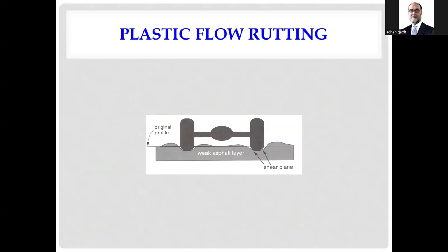Now how do you see where the rutting is? If your asphalt is weak, then the depth of the failure will remain in the asphalt layer, will not penetrate. So that indicates even though base and sub-bases are strong, subgrade is adequate, it's the problem with the asphalt layer. One may be use of inadequate asphalt binder.